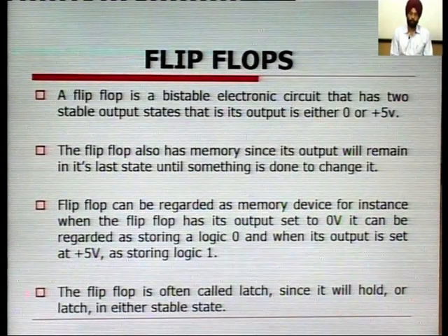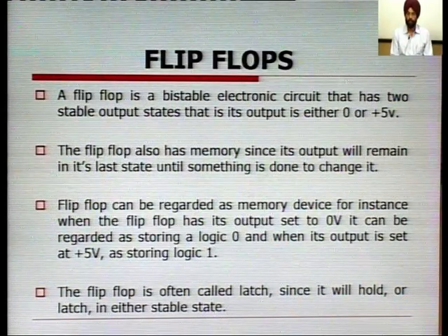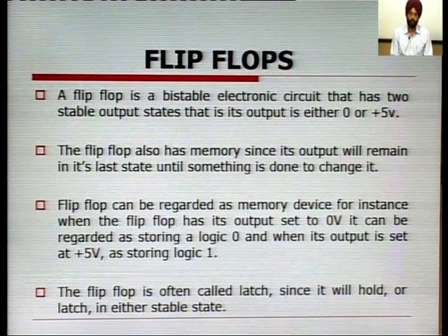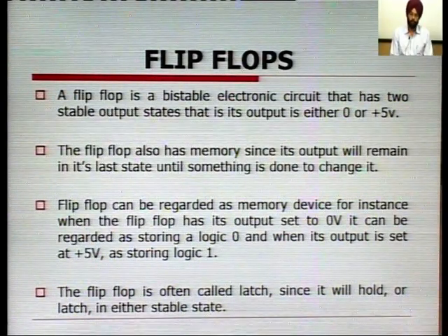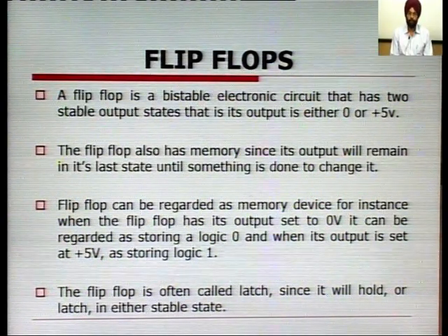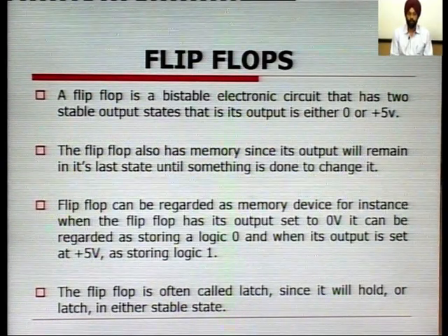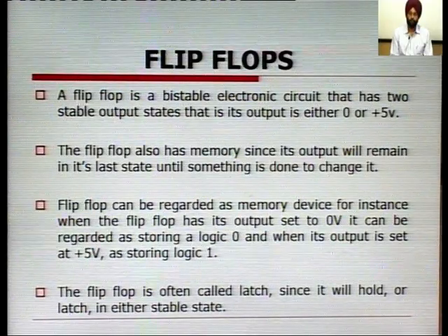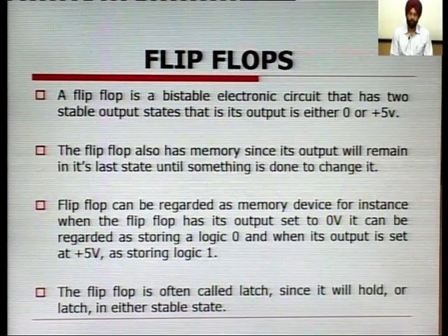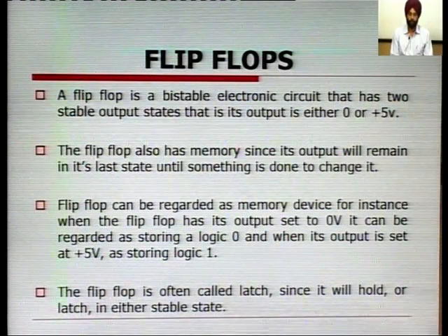Now, what is a flip-flop? In a combinational digital circuit, the output of the circuit is dependent upon the current input, but the circuits which have memories are called sequential circuits. So, the flip-flop is the main part of the sequential circuits in digital electronics.